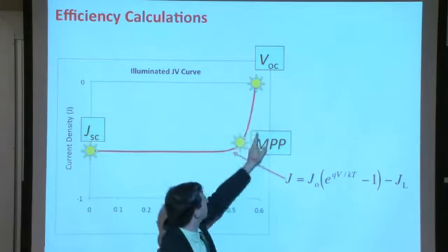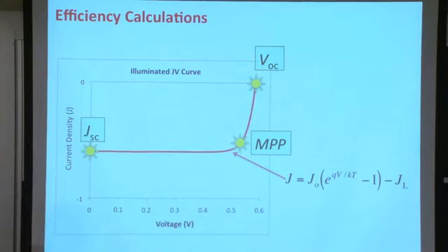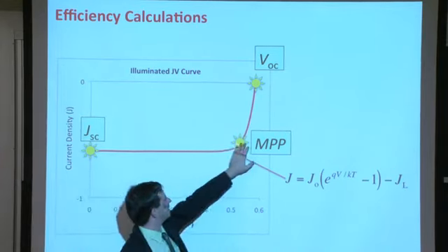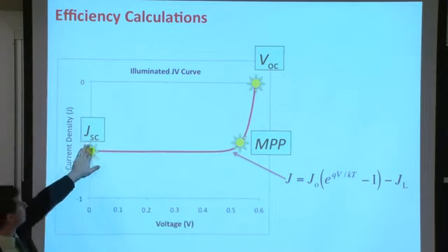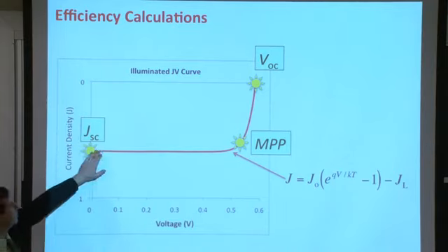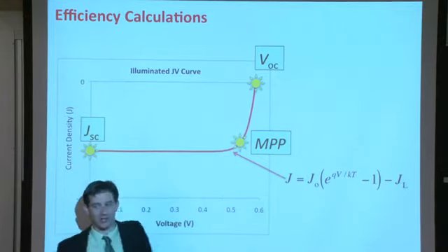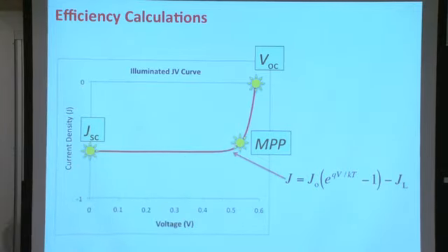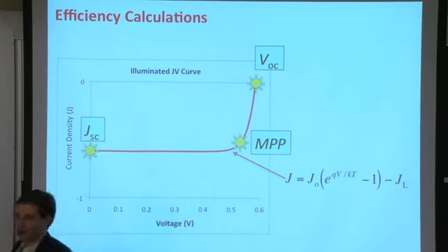Open circuit. And voltage, because it's an interesting point because it's the maximum voltage here represented in the fourth quadrant. And somewhere in between the point of open circuit voltage and short circuit current, short circuit current, again, because you're short circuiting your device, current is flowing through, but there's no resistor, there's no external load, there's no power being deposited on external load. Somewhere between these two extreme conditions where there's no power flowing through the external circuit, you have a maximum power point where there is a power being deposited across your external circuit and a lot of it, right? That's the maximum power point. This is the point at which the solar cell is producing the maximum amount of power output.